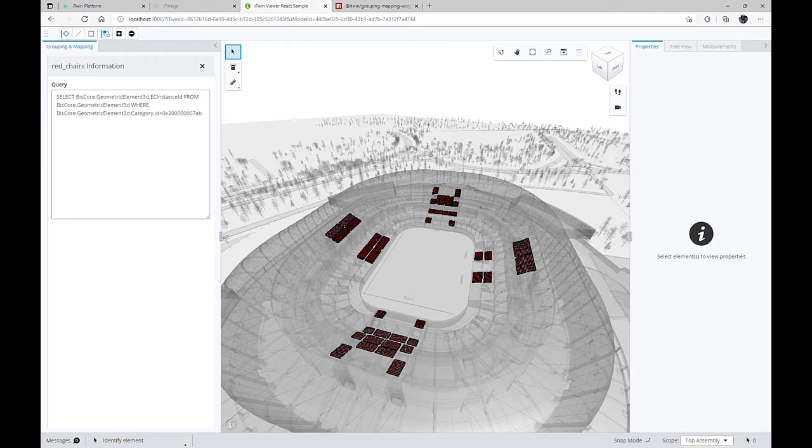Now, the complexity of the EC SQL query is completely up to you. What we're seeing here is a relatively simple example, but EC SQL queries to capture more nuanced subsets of the data from your iModel can easily be much larger than I can show on the screen currently. And for your purposes, if you are experienced with EC SQL, you feel comfortable with it, please feel free to use our APIs directly and build groups yourself.